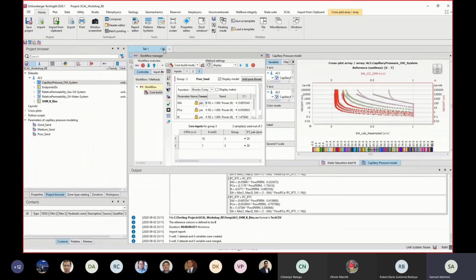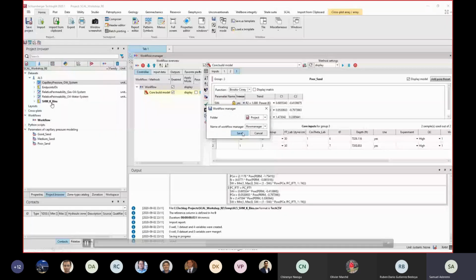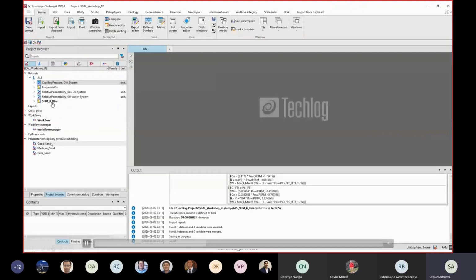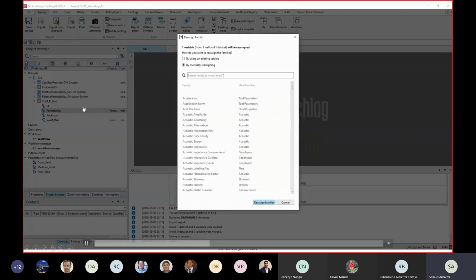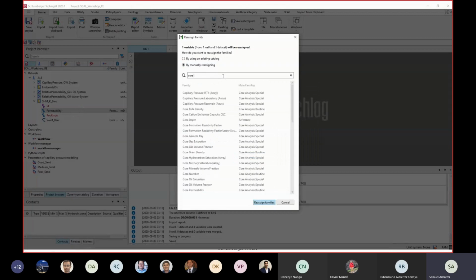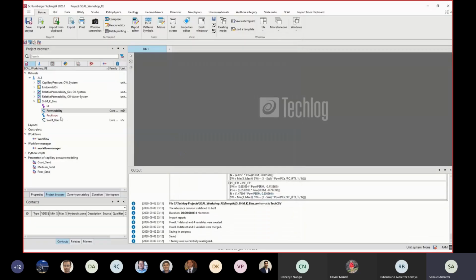The next thing that we want to do is generate the relative permeability for these bins and generate the capillary pressure for these bins. The capillary pressure will be from the saturation height modeling. Then finally, we'll combine both the relative permeability and the capillary pressure to give our table. It's a lot of interaction, this particular one, but we do quite a lot too. Those of us who use this workflow in Excel find it pretty straightforward, and I'm sure this will be automated as we begin to use it more and more.